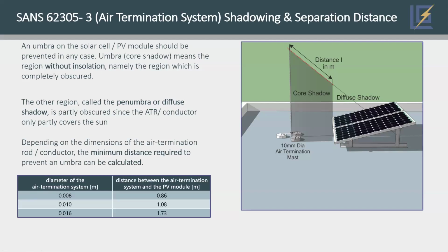We can't be a meter away purely because the parapet, which is the side of the building, is 500 mil away. So now comes the question, how do you do it? That is exactly why many installers will opt, like in the video, to put air termination rods below the panels. That is a big challenge we have in the industry when it comes to lightning protection for rooftops.